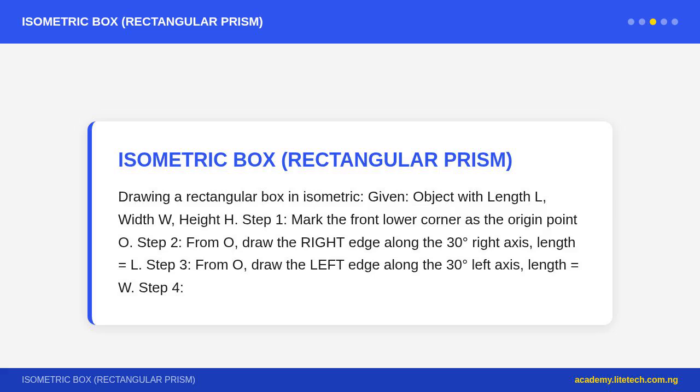Method. For center approximate ellipse, most common method for WAEC. Step 1. Draw the isometric square, rhombus, that would enclose the circle. For a circle on the top face, the rhombus has sides equal to the diameter, with 30 degrees axis. For a circle on the front face, the rhombus uses the vertical and 30 degrees axis.